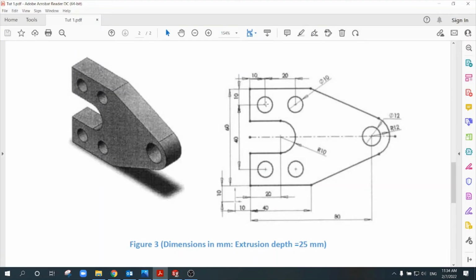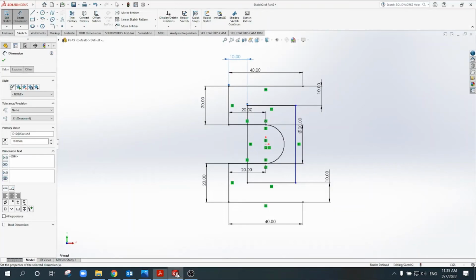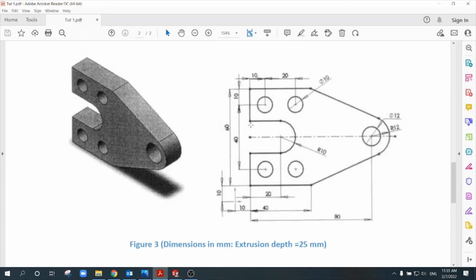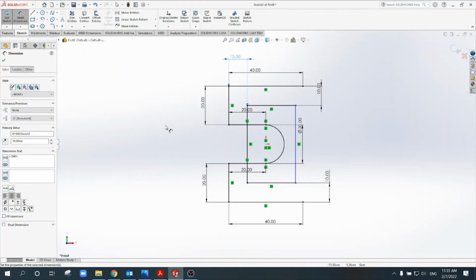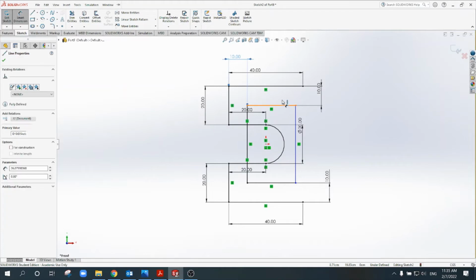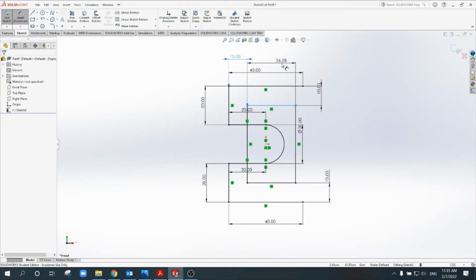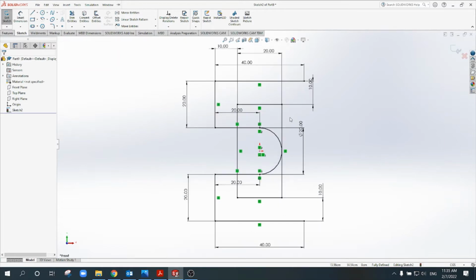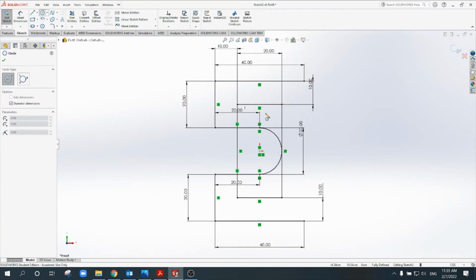It says the corner of that rectangle I made. I want to make a rectangle, so to create the circles in the corner. So in this case, I'm left only with the distance between circle 1 and 2, which is given as 20. That means I have to define this distance to be 20. So I'm done with the corners, and I just have to create the circles. Their location is fully defined.